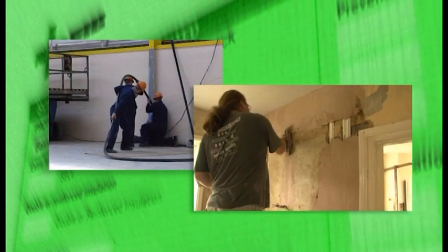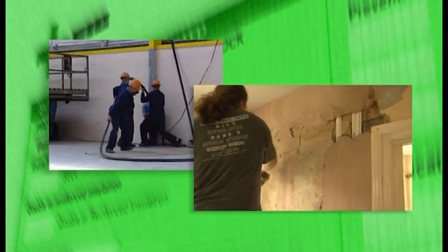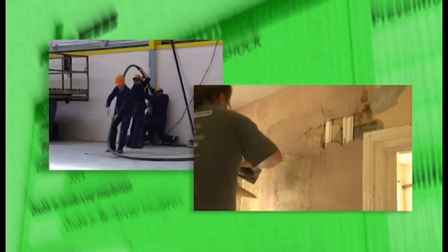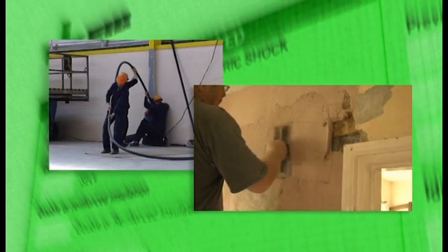For many installations, it's actually during the construction process that they'll be subjected to a higher risk of mechanical damage and external influences, such as dust and water, than they will during their normal working life. So the inspector should check for this damage before equipment and cables are concealed, and ensure that they're replaced if damaged. We now reach the final item on the checklist: selection of appropriate functional switching devices.